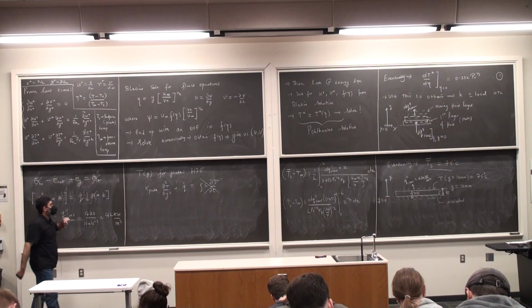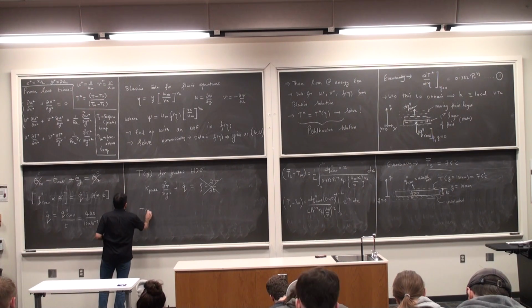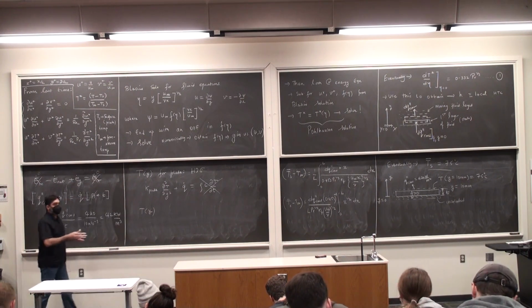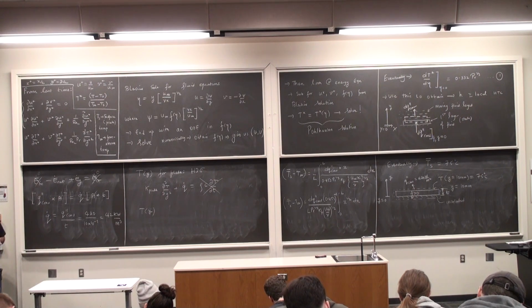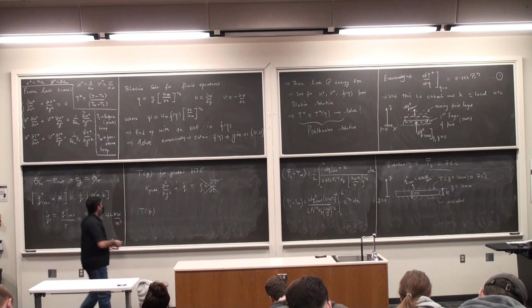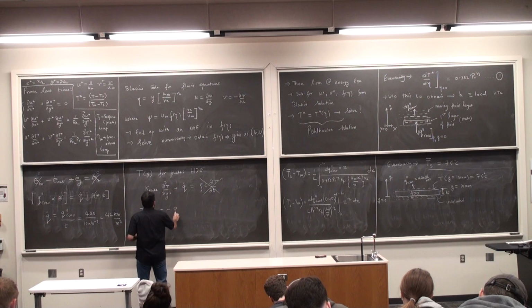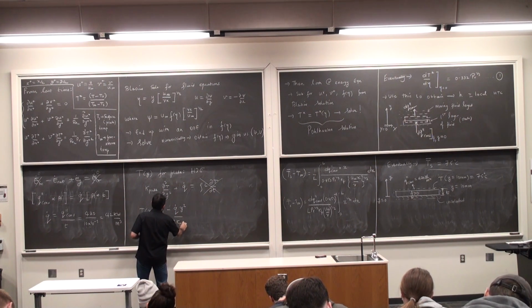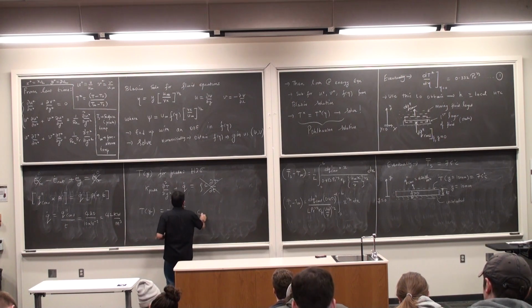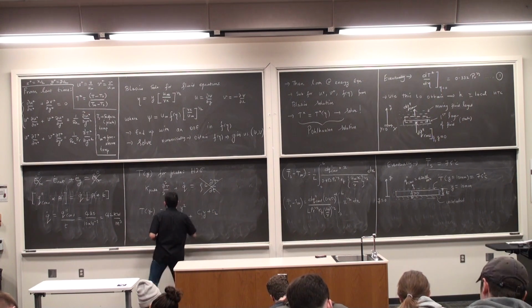So that becomes a quadratic, which you have solved for in multiple places in your exams and in your homework. So we will skip all the details. This is T equals minus Q dot y square by 2 K plate plus C1 y plus C2.